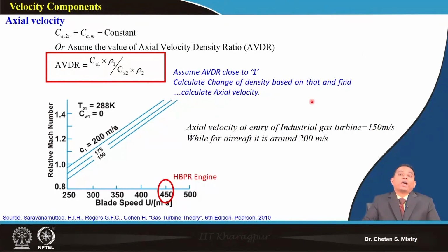And in order to address this issue, they have introduced this axial velocity density ratio parameter. In some of the cascade tunnels, they have kept some flow control mechanism like flow sucking mechanism, some corrugation, on both the walls, and that's what led to reduce this variation. Okay, so in many designs they are using this kind of concept also, that's what is called axial velocity density